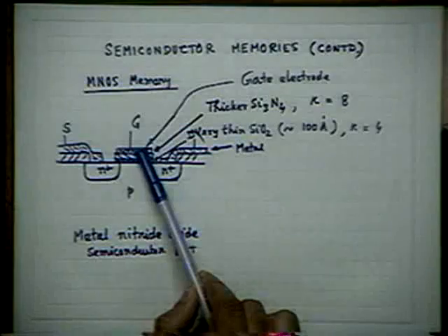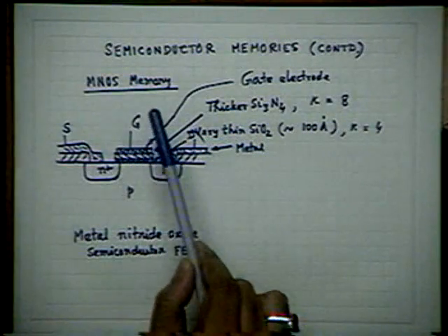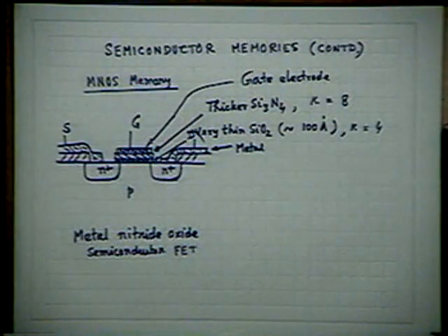So I have to provide some lines into the circuit to apply relatively high voltage, maybe of the order of 30 volt, 25 to 30 volt, for a very short duration. The duration, etc., has to be adjusted according to the manufacturer specification for the operation. I want a reliable on and reliable off. That's important. So that the device gets turned from on to off, I apply a high voltage here for a very short duration.